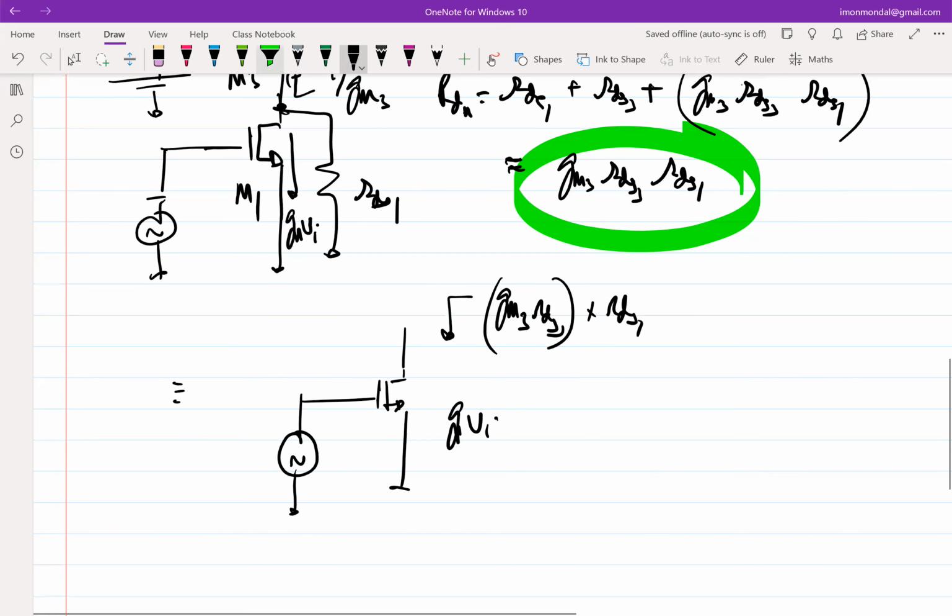Right? It would seem like a box. You don't know what is inside the box. If you only look at the gains and the short circuit currents, or the Norton equivalent, it would seem like it's a common source amplifier which has a GM equivalent to the GM of M1, but it has an output resistance which is RDS of the transistor times some factor, right?